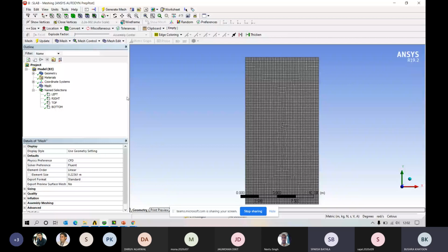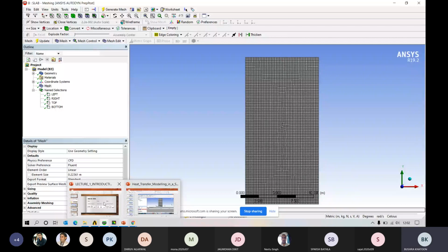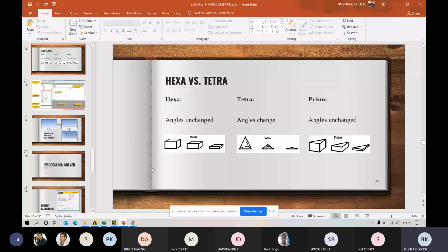अच्छा, मतलब मैम जैसे आप पाइप का बता रहे थे, तो पाइप में अगर हम एंट्रेंस का देखेंगे तो हमें एंट्रेंस लेंथ तक कुछ अलग मैशिंग करना होगा और उसके आगे कुछ अलग, तो ऐसा पॉसिबल हो पाएगा ना? मीन्स आप किसी भी तरह से मेशिंग करना चाहते हैं आप कर सकते हैं, इसमें कोई इशू नहीं। बस ये कि आपको नॉलेज होनी चाहिए कि कब कहाँ पे किस चीज का यूज करना है। यहाँ पे ऑटोमेटिकली बाय डिफॉल्ट हमारी ज्योमेट्री के अकॉर्डिंग हमारा मेश जनरेट हुआ है। अगर आपके पास कॉम्प्लिकेटेड ज्योमेट्री है, देन उस केस में आपके पास डिफरेंट मेशिंग ऑप्शन होते हैं। जैसे आपकी कॉम्प्लिकेटेड ज्योमेट्री सर्कुलर है या स्क्वायर है, तो वहां पे ये ब्लॉक टेट्राहेड्रल मेशिंग अलाउ नहीं करेगा, वो अच्छा रिजल्ट नहीं देता है। उस केस में आपको यहाँ से डिफरेंट टाइप ऑफ मेशिंग चूज करना पड़ेगा। मीन्स हेक्सा, टेट्रा, जो भी रिक्वायरमेंट है आपकी ज्योमेट्री की, उस बेसिस पे आपको चूज करना होगा।